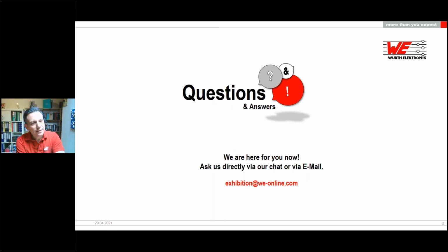Maybe the answer is, there is not an industry standard right now. We have, as mentioned, CE and EMI certifications and also the RED. The standards themselves, the WPC, the Wireless Power Consortium, are working also on these power classes like mid-range, so over 30 watts, up to 200 watts, up to 2.2 kilowatts. But they are still working on the standard. So in the market, there is no industry standard right now. That's the reason why we have set up this proprietary system, to give a very easy step into wireless power technology for your applications up to 200 watts.